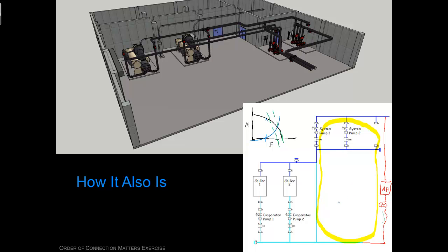The whole reason we did that was it lets the distribution pump energy vary with flow. At high loads, you'll move a lot of water and use more energy, depending on if you're using a variable speed drive or just moving around the curve. Then as the load drops off, you reduce the energy requirement. So that's a good thing. And this design evolved as the first energy crisis hit.